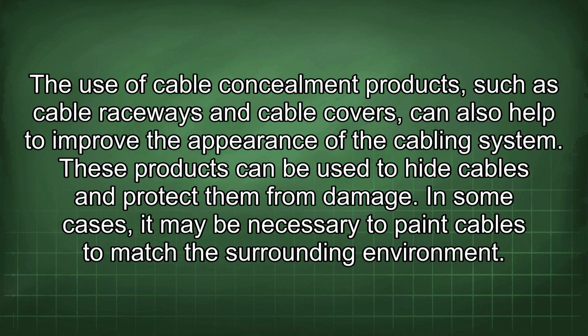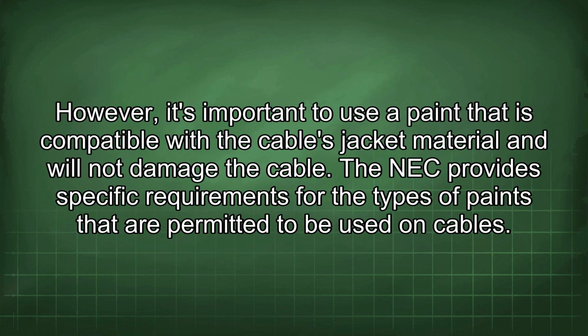In some cases, it may be necessary to paint cables to match the surrounding environment. However, it's important to use a paint that is compatible with the cable's jacket material and will not damage the cable. The NEC provides specific requirements for the types of paints that are permitted to be used on cables.